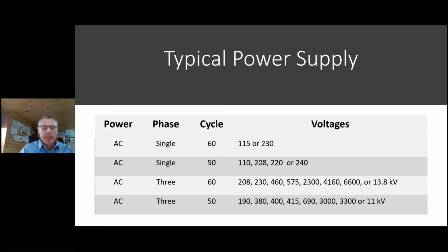Depending on the age of the plant and the infrastructure, there may be some 2.3 or 2300 volt supply systems, and we don't see too much request for those motors anymore, but they definitely exist, and they're still very much available. And just to wrap up on the last line, in the 50 hertz world, there's a combination of voltages there. So hopefully that makes sense. If you're in the manufacturing business and you're exporting, you will see requests for these types of voltages.